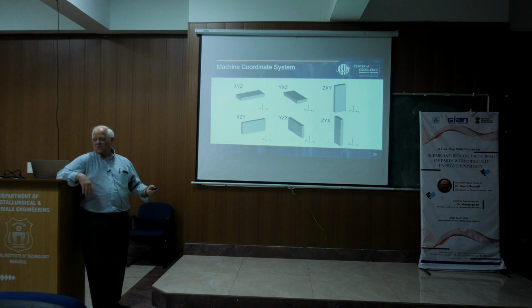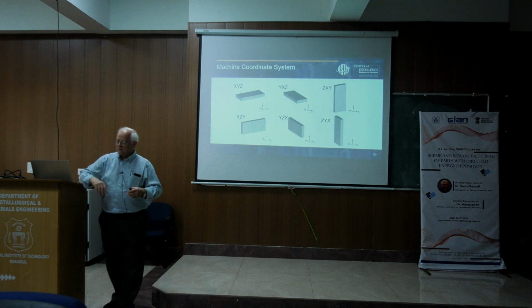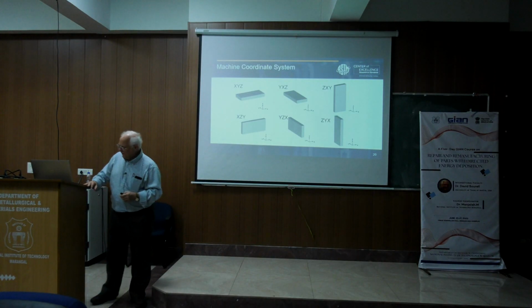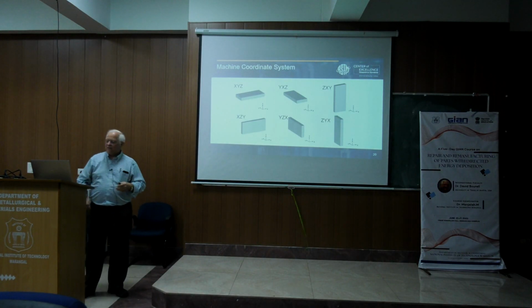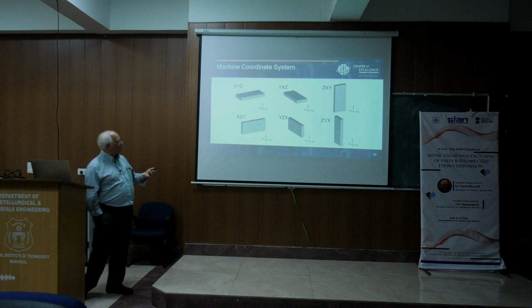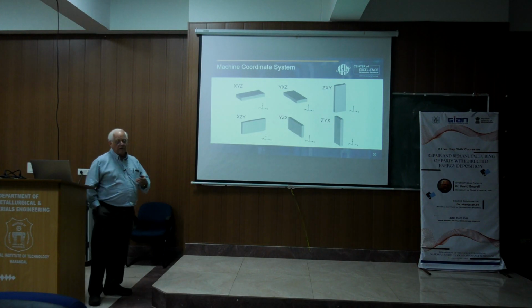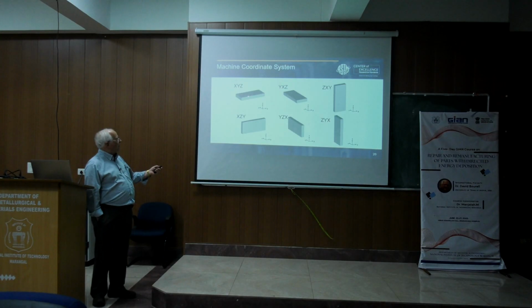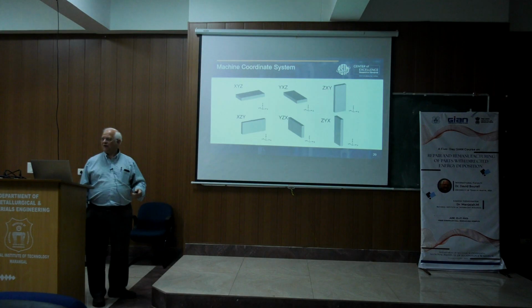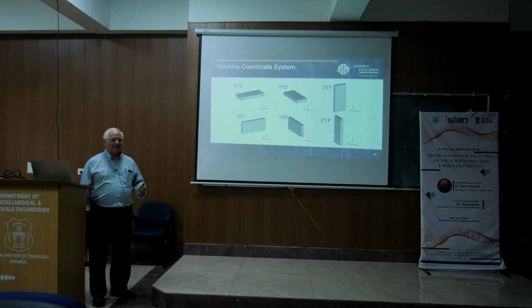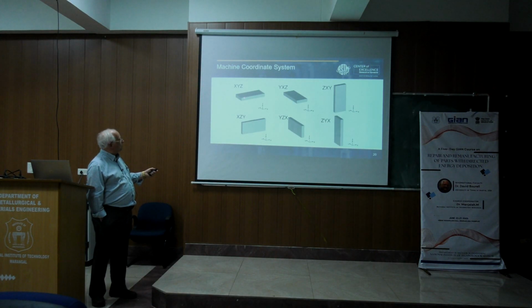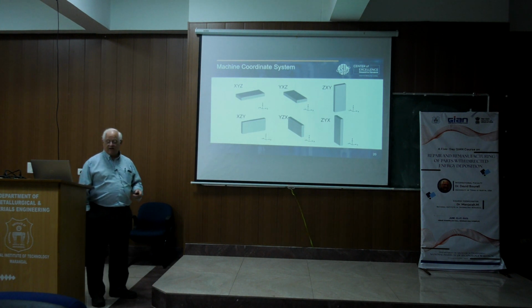You see how this works, right? So we can describe the orientation this way. So that's one simplification. There's another obvious simplification that we can do, and typically we will do this for rectangular shaped parts, because the third letter is completely redundant, we can drop the third letter because there's no value in adding it, right? So what we can do is we can call this an XY part, call this a YX part, this would be a ZX and a ZY part.